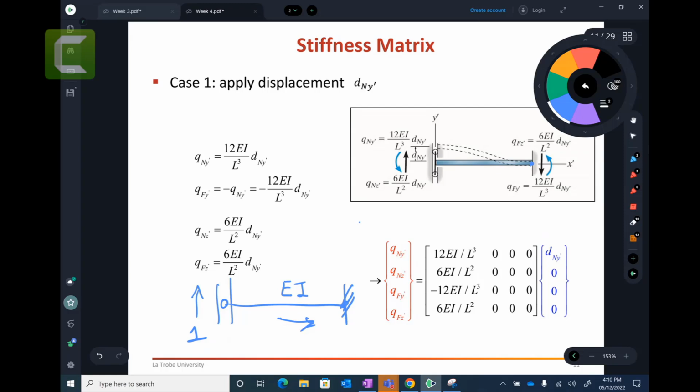Because the beam could be made of steel or concrete, or if you have electronics people, they may be made of some kind of polymer or something. So they have a Young modulus. It can be any value. And who is going to give it to you? Your manufacturer. The suppliers may know this Young modulus value. If you have materials which you don't know, you can go in the lab, do the tensile testing, and calculate the Young modulus. Now, what is I?